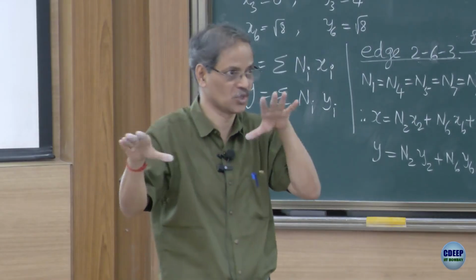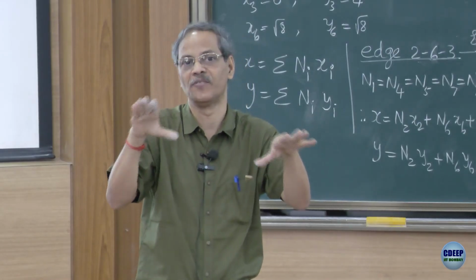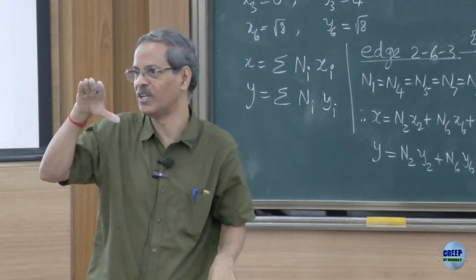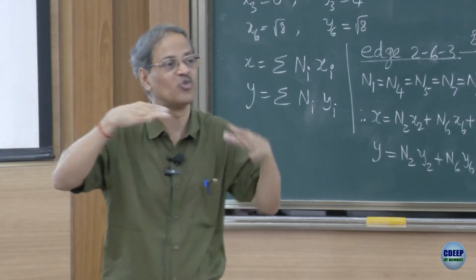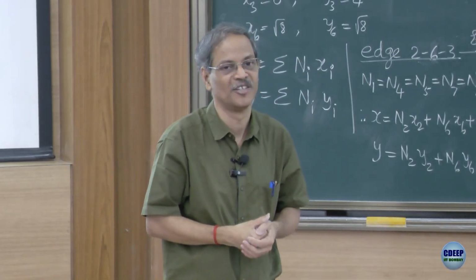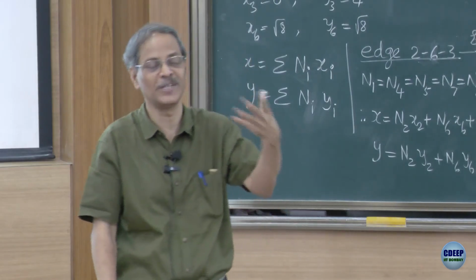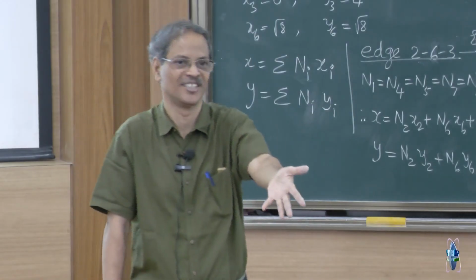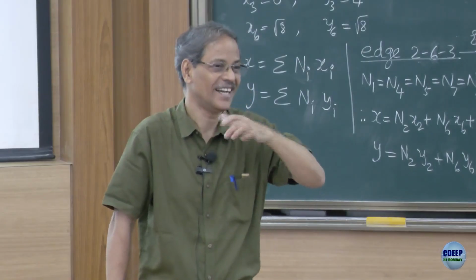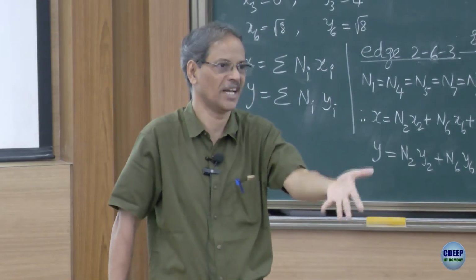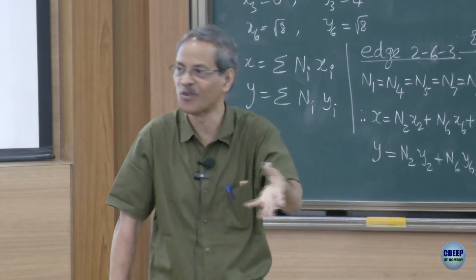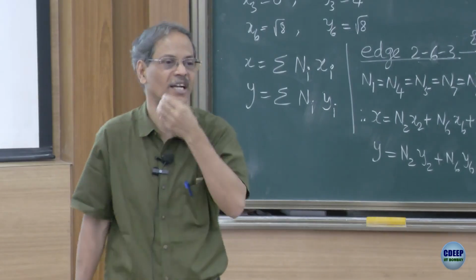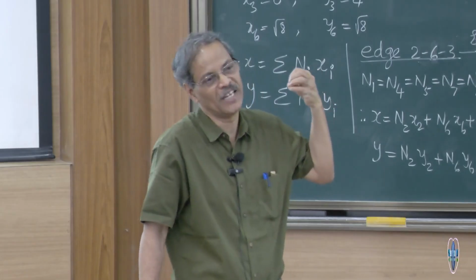So do not get confused between these two different problems. One is modeling the geometry, the other is modeling the field variable. It is for you to decide in the problem whether a sharper change in the geometry in the given location in your course project topic that you have taken is a significant feature in my design that I should be worried about. Failure will happen there, and I need to know accurately everything. Therefore, I need to use a very refined mesh there.